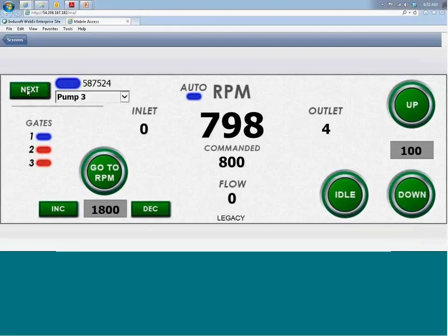One network communicates exclusively with the engine, pulling information from it and telling it where it needs to be and where it needs to throttle and how it needs to throttle and the torque that it can run at. And then the other CAN network interfaces with the rest of the control system of the I/O. There's not a whole lot of proportional control. There's a lot of digital.